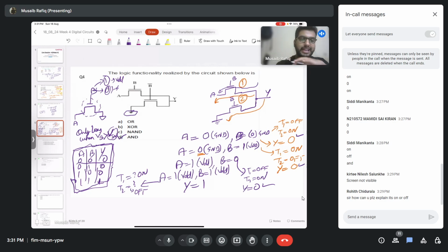So it means it's basically a switch. When input B is 0, my transistor is off, and when input B is 1, my transistor is on. Basically, the voltage at the gate terminal should be greater than some threshold voltage. I won't dive into the operation details of why it turns on after some particular voltage. It will require some basic knowledge about electron devices, some concepts of accumulation, depletion, inversion, and once the channel forms, there is conduction after we apply the drain voltage.